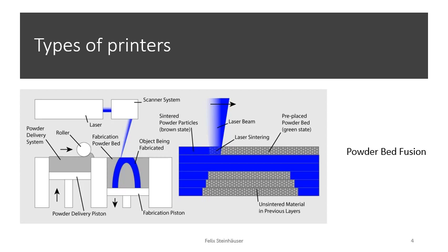To start the process, you have different possibilities of heat source. Either you have a laser or an electron source for electron beams. So this is the first difference in powder bed fusion. There are three different main types of powder bed fusion. You can use electron beam melting, direct metal laser sintering, or selective laser melting.